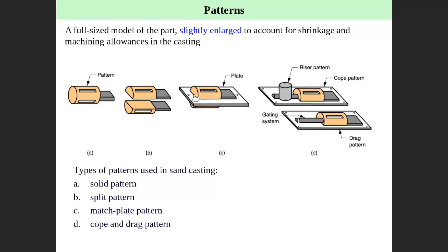You bring two plates, one up plate and one down plate. You put a pattern in the plate. Why do we do that? Because we need to assemble here. This is a riser. This is a runner. This is the additional part we need to add. This is a riser, this is a runner, this is whatever item here for up and down. Then you have two plates, one for up, one for down, and then we add all the details. Then when you put in the sand, all these details will be created in the sand, right?